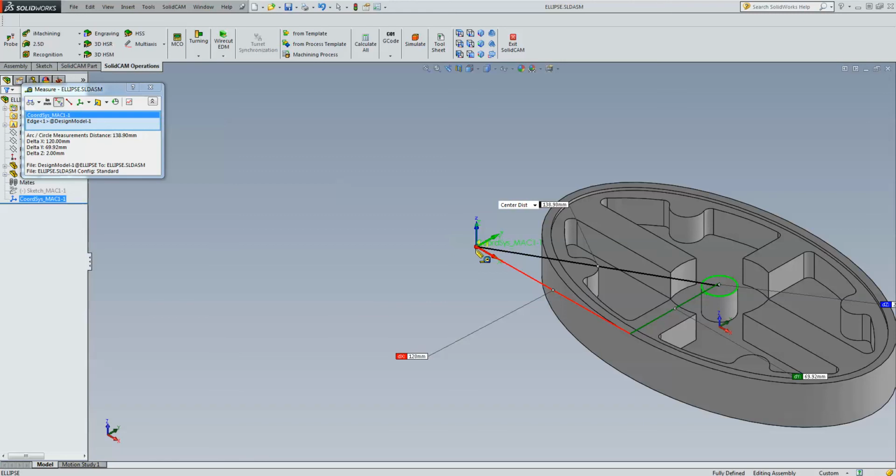Okay, that's basically the end of the webinar. Let me just go through, I see I have a question on the screen, and it goes into the chamfer recognition. Does chamfer recognition only work with faces that are perpendicular? If it's on a slight angle, it will pick up the edge of that as well. Okay?